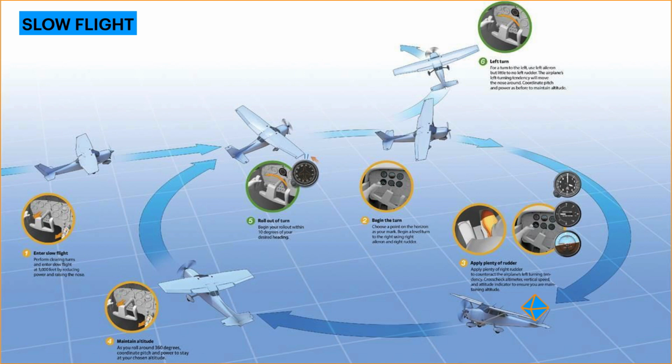When operating deep in the region of reverse command and approaching a stall warning, lower the nose to regain airspeed, but also add power to maintain altitude. Flying on the back side of the power curve will result in high angles of attack and require high throttle settings similar to those during takeoff. There will also be considerable left-turning tendencies, which will need appropriate rudder input to be neutralized.